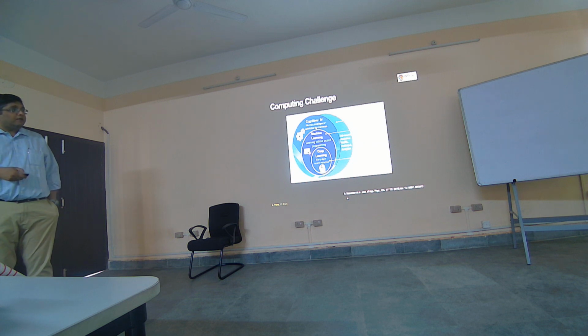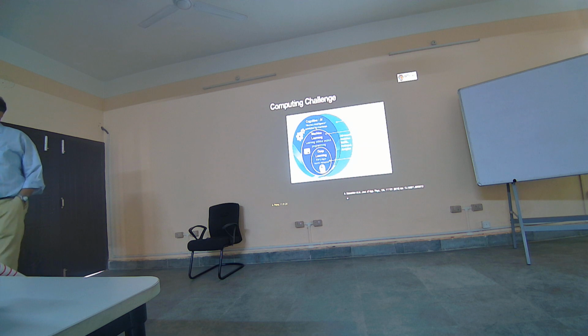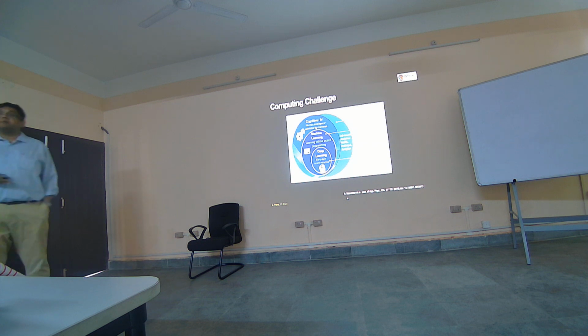So this is where there is a lot of demand for energy efficiency, because this is going to be in the ASIC field. It's not going to be a generic server or a GPU, but an ASIC, and the ASIC is needed because that's going to reduce your cost. If you do everything on GPUs or FPGAs, it ends up being a very expensive proposition. So the question is, how do we put this technology on standard CMOS technology in an ASIC at low cost to get the maximum benefit?